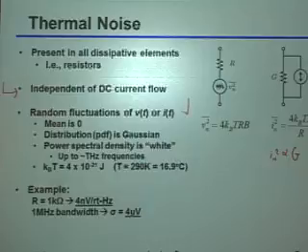So as we've mentioned a couple times, but I'll just reiterate to make sure it's absolutely clear to everybody, remember, when I'm drawing these circuit elements here, you should not treat them as a deterministic voltage or current source. You should remember this is really modeling a random process. Okay? So even though you've drawn these elements the same way we would draw the other elements, and in fact you'll do many of the analyses in a very similar way, you really have to keep in mind that these are random sources. Okay? And we'll say some more about that in a second.